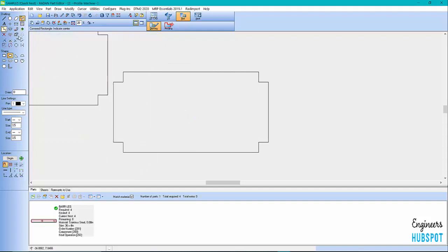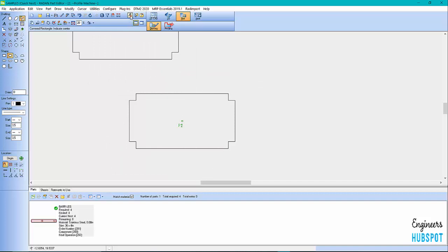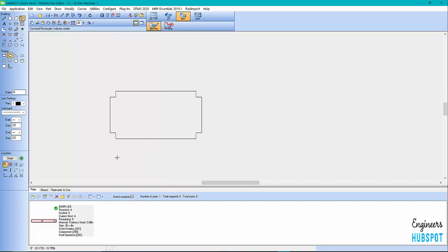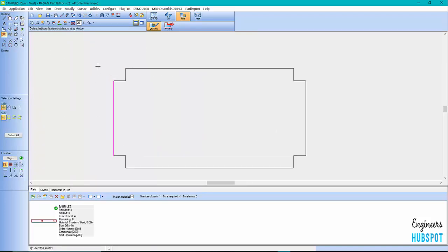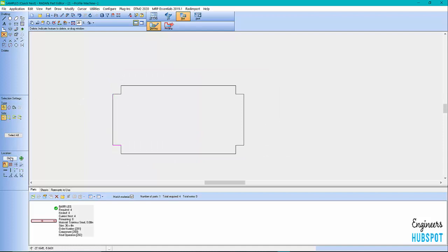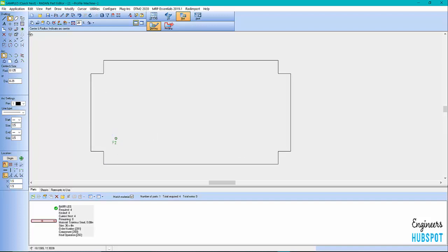Right, so you can see I've got the cursor on here. If I hit this one, it cancels that. But maybe if I had something else on there and I wanted to keep using it, I could keep it on there. Okay, and then we've got our new drawing. Now we can come in and go, here's my origin, and then I want to put a circle or a diameter, and I'll go origin there, and we'll go 1.5, enter, 1.5, enter.